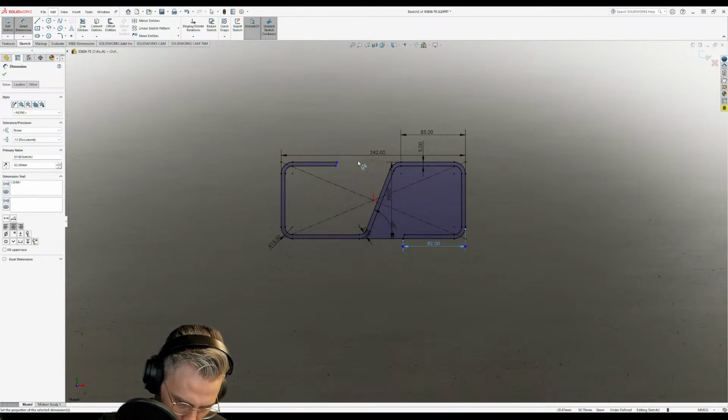I'm going to measure the fin stack on either one. I've got to be careful not to compress them, though, because that will distort my measurement. I'm using a pair of calipers on it. It's about 51 mil. And this side here is about... Actually, you know what? It is noticeably shorter. Interesting. Very interesting. Okay.